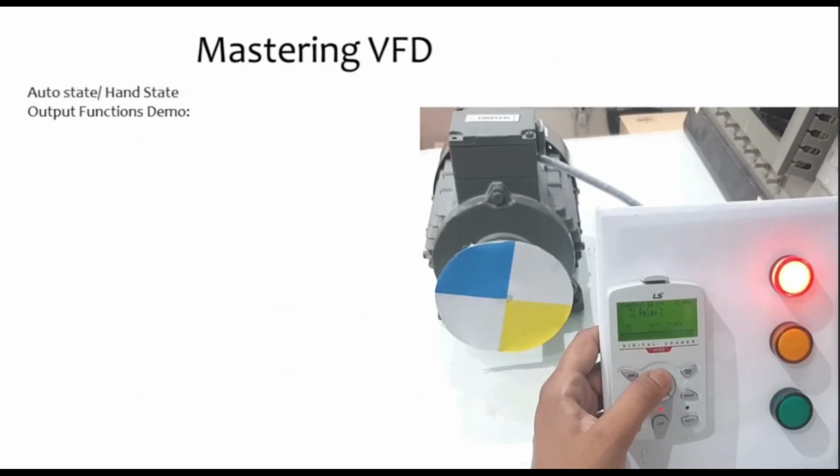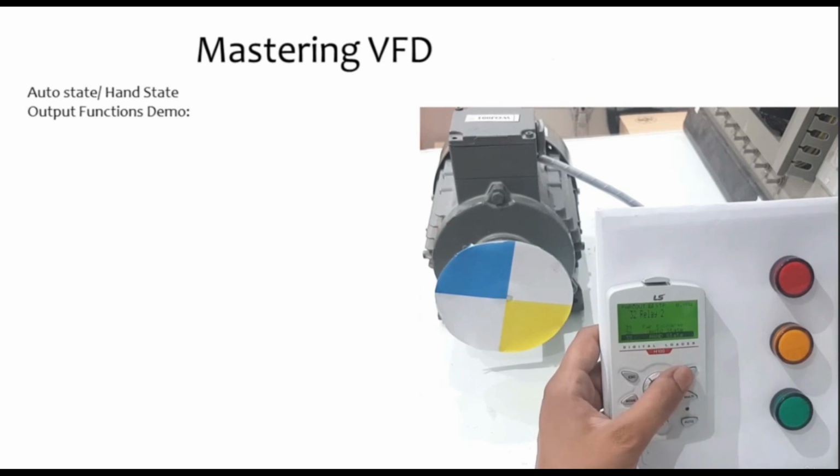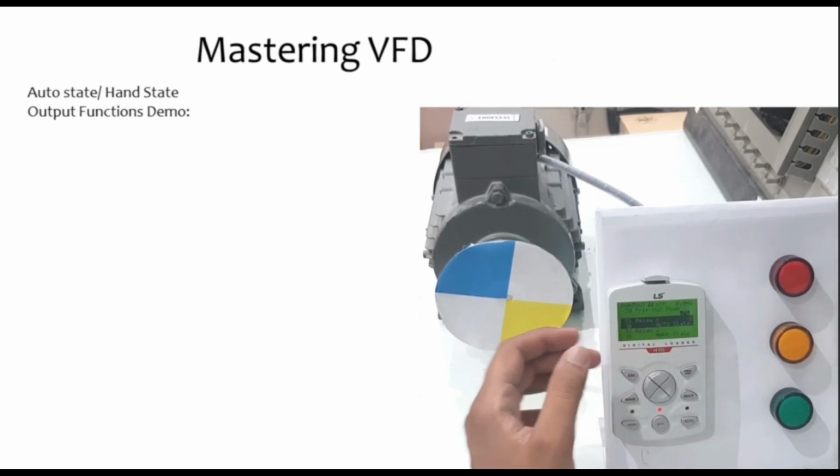This is another demo. This VFD model has auto and hand keys. So in case we need indication of auto state or hand state, we can easily assign outputs. Relay number 1 I will program as auto state, and relay number 2 I will program as hand state. And third relay I will keep it as run function.